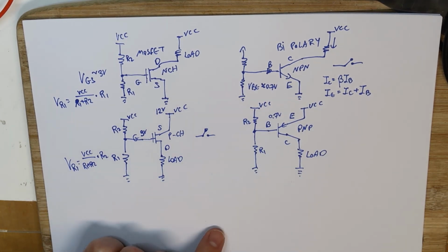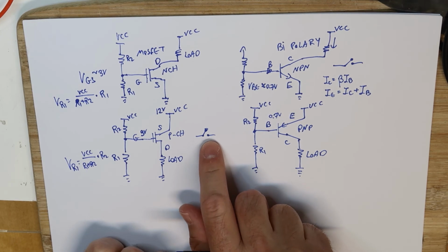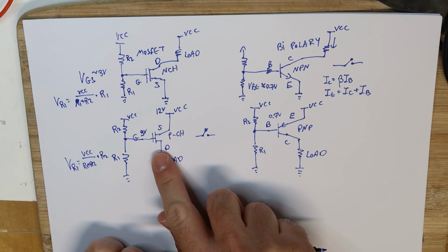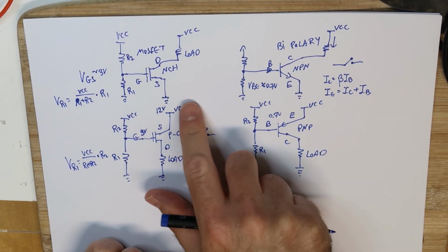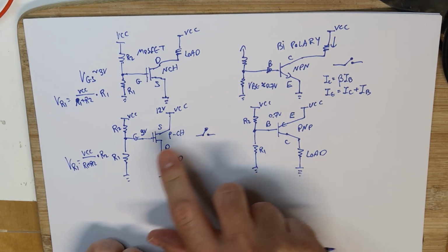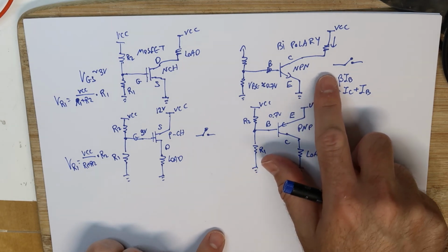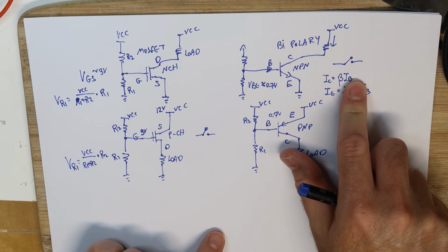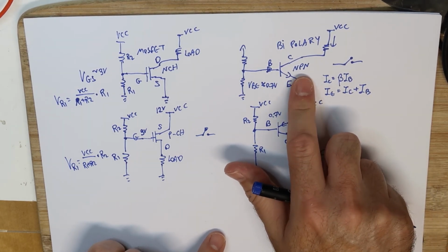There are some minor things that we need to be aware of. In order to work in the switch way, we need to have a VGS that is greater than 3 volts, because generally MOSFETs also have resistance that can be similar to this NPN, that can work as an amplifier and not as a switch. So this can work as an amplifier or as a switch.